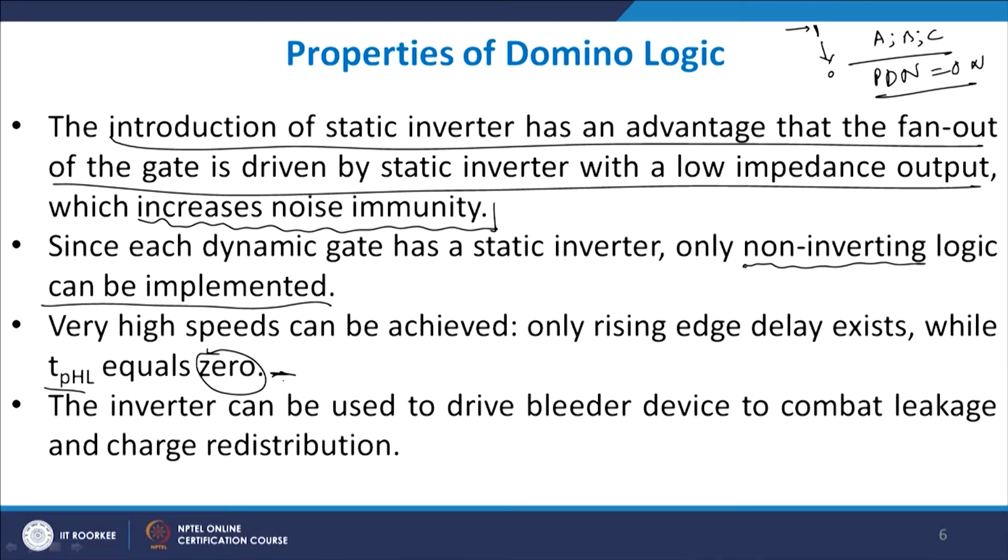So, these are a few properties of domino CMOS logic. One way to solve this non-inverting problem of domino logic is to reorganize the logic using simple Boolean transformation.